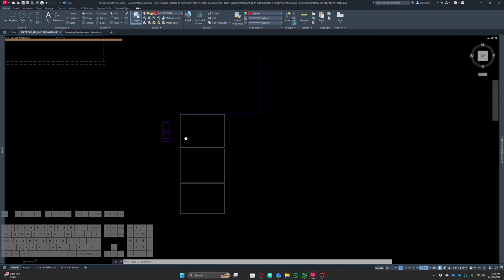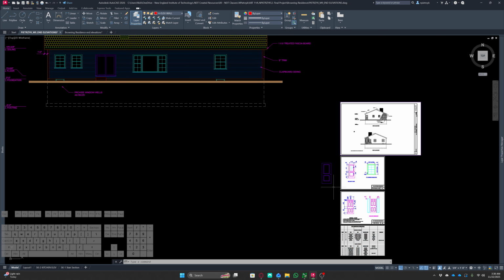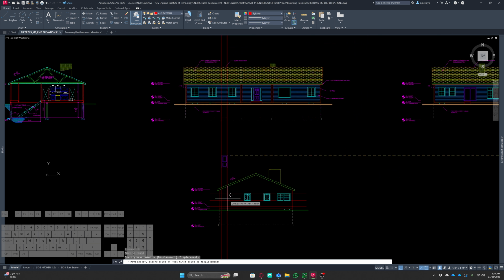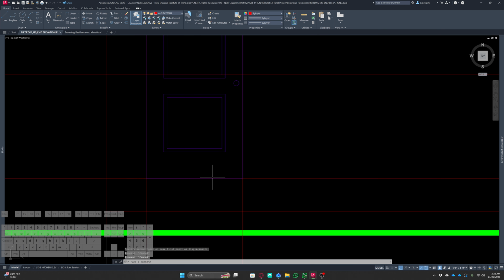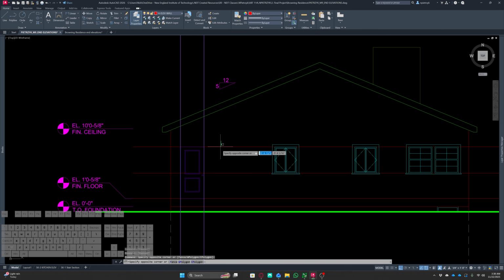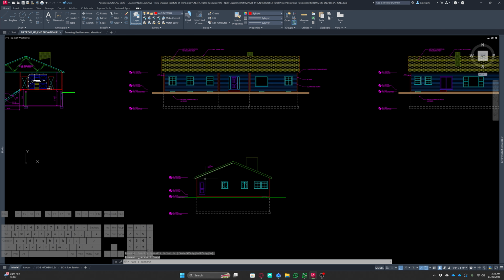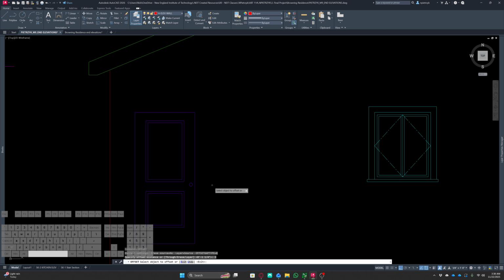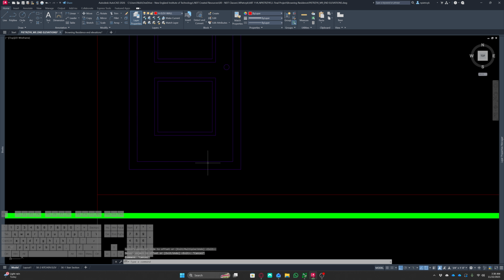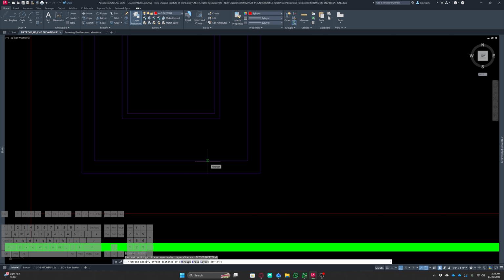Good luck. Anyway, I got this door designed, and I'm just gonna grab it. And I'm gonna do a move command, and just gonna move it straight into place perfectly. What I will need to do is I'm going to do an offset of 3 around it. And I'm going to do an offset of... Oh, math is not mathing, huh? 1.25 or 1.5 rather. 1.5 inches.